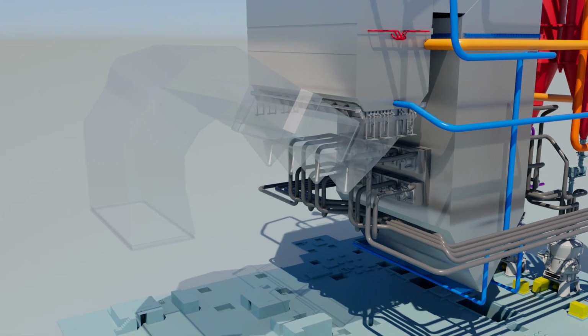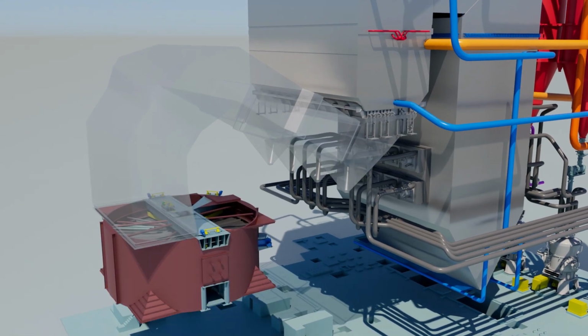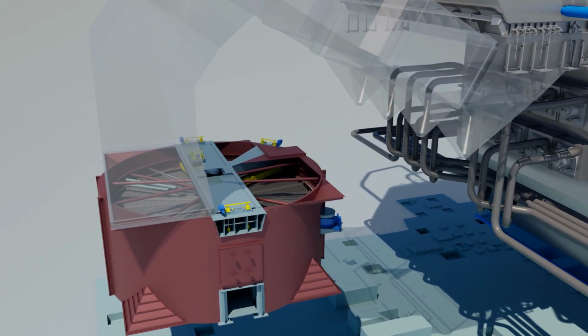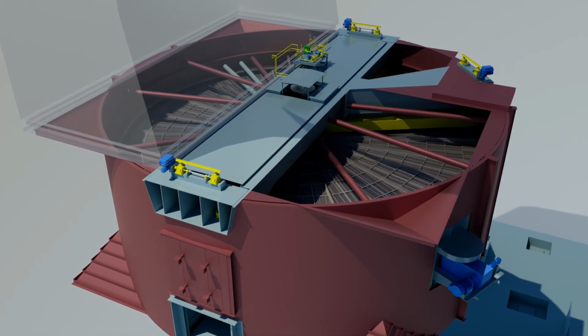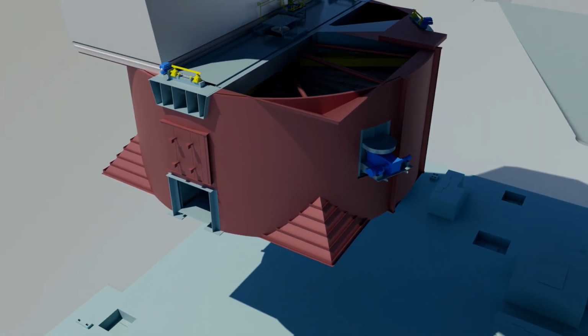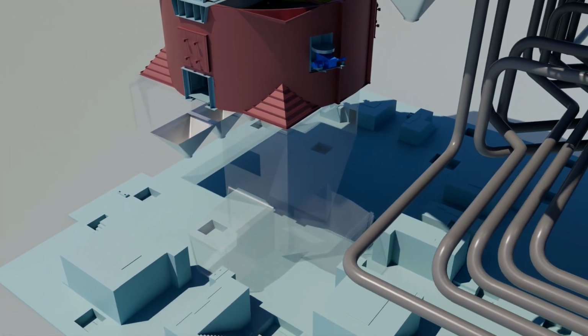Air preheater is provided for reducing the flue gas temperature to recover the heat energy of the flue gas at the boiler outlet and to raise the primary air temperature to dry up the moisture in the coal and raise the secondary air temperature.